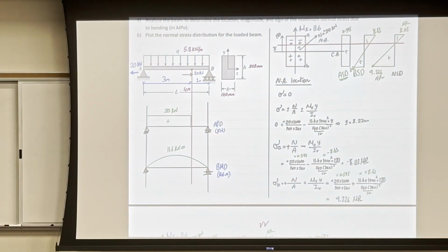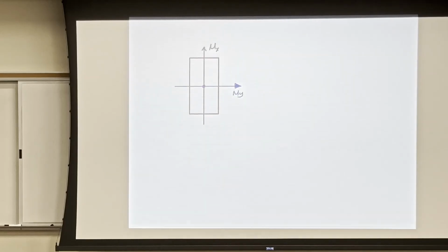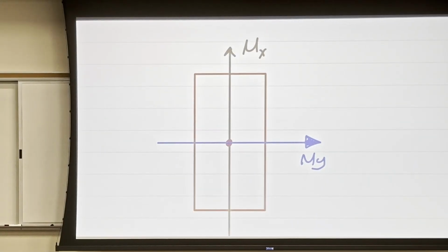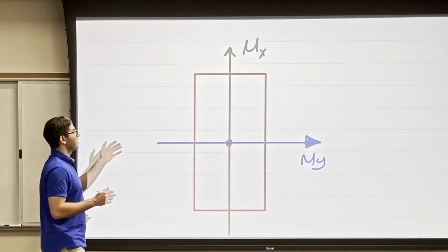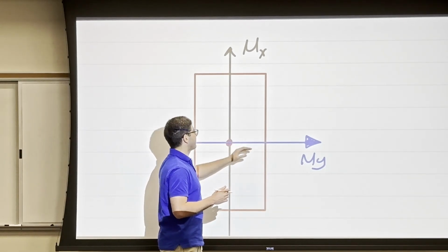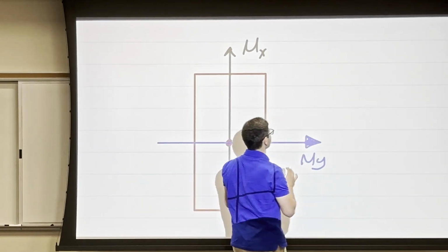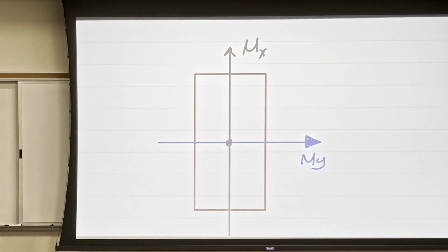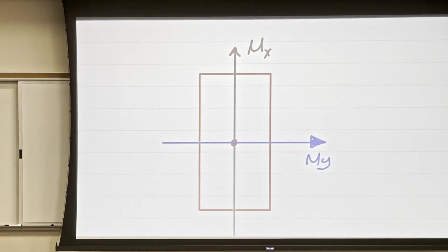And finally, if I do have the biaxial, where I do have two moments, it's called biaxial. If I only have one moment, it's called uniaxial. So if I have two moments, and I do have, let me put here a normal force of, let me write it positive, for example 20, and let me change the color so that I can put the signs inside the graph.